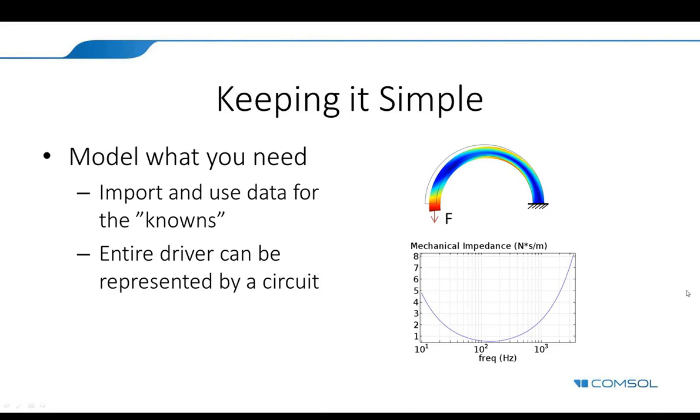One thing you could actually do, it turns out that if you were to construct this loudspeaker in reality, this peak would probably be slightly less pronounced than what it was in my curve, and that's because you get some additional damping due to the really, really thin gap that you have between the voice coil and the former. And that damping is something that I'm not modeling in the model right now. I could model it by using thermoviscous acoustics. It's not that hard to do. It's just not included in the model that I set up for you.